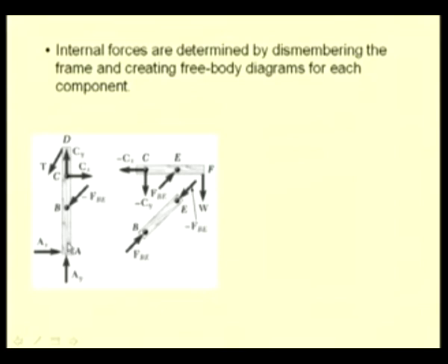So, we have the free body diagram of the multi-force member A, B, C, D, where we have the pin reaction at A, the force from the two-force member F, B, E, which is of known direction but unknown magnitude, and at C we have the pin reaction coming from another multi-force member. So, this pin reaction is unknown in both magnitude and direction, and at D we have the tensile force of the string of unknown magnitude and known direction.